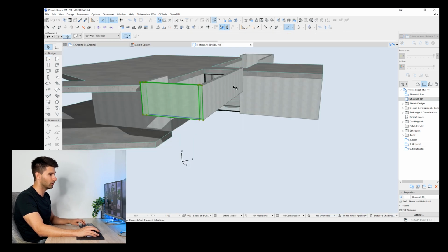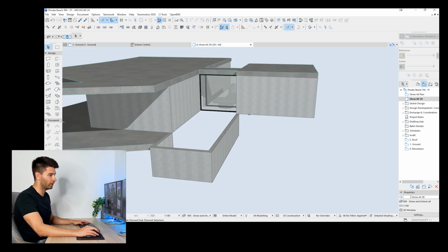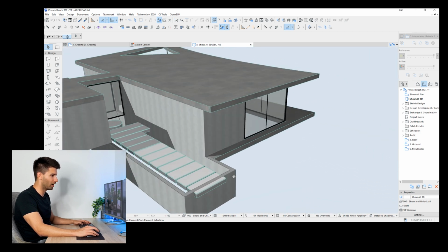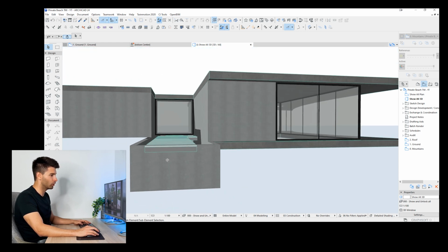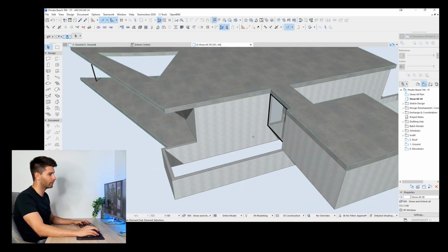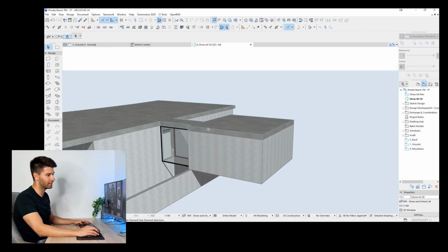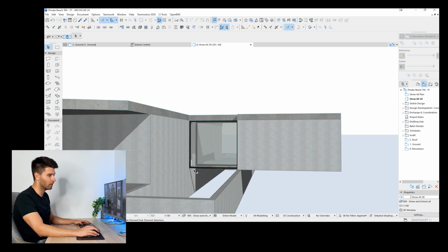So if this was the pool, it is way too high up again. So we will just lower the pool so it sits at natural ground level, and we will then create a slab that connects the two. So that'll be our lap pool now. It'll also form part of our actual entry and its statement itself. So these stepping stones will go through the pool. This section of the pool will only be a couple 100 millimeters deep, and then it will rapidly drop down just underneath that tree and underneath the house to 4 meters deep or 2 meters deep, whatever we decide to make the pool, and making sure we leave enough clearance under that house so the water is never touching it and it is a literal bridge over the top.